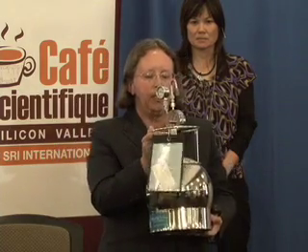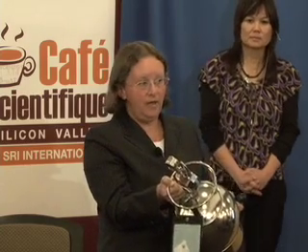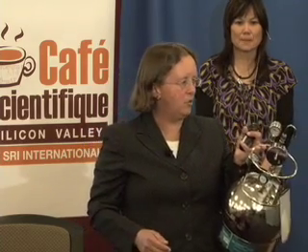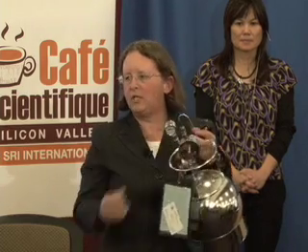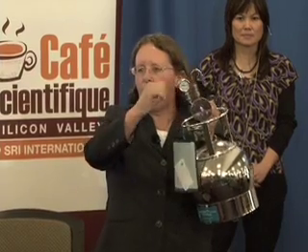And so the way we get this from the lab: first they clean it. It's got to have absolutely no contamination in it. So they clean it, they bake it out, and then they negatively pressurize it at the lab. So it comes to us at about minus 30 psi. Then we'll attach one of these flow controllers, and the flow controllers are set so that once we open the valve, it will draw in air over whatever time frame we specify.